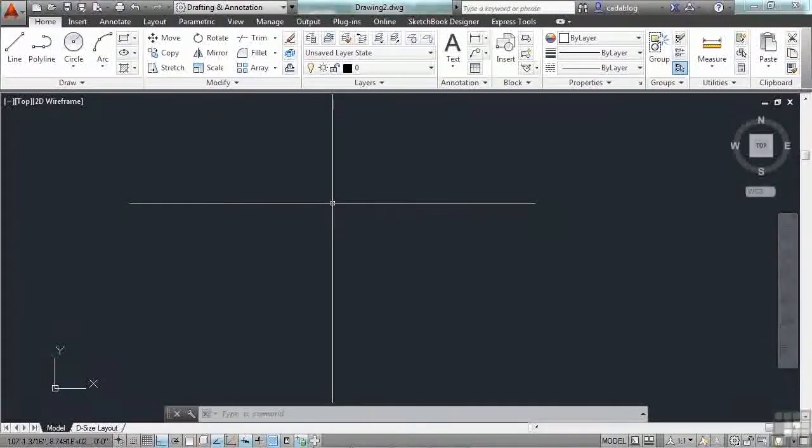You can draw a polyline, or p-line as they're often called, just using coordinates, relative coordinates, polar coordinates, length, just two points, etc. Lines can also be drawn as arcs. You can even switch from line to arc while you're drawing a polyline. And when you go to edit them, you can do the same thing. Polylines are very versatile and have many functions. In fact, I know several CAD drafters that don't use lines. They use p-lines because you can do things with them that you can't with a regular line.